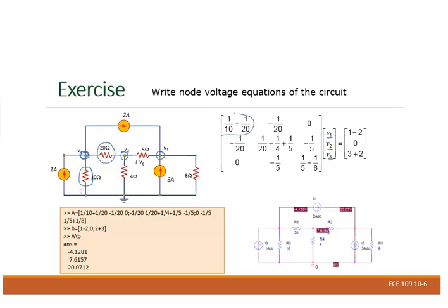That's what you have right there. Between node 1 and node 2, we have 20 ohms, so you're going to have negative 1 over 20 here. Between node 1 and node 3, we don't have any elements, that's why it's 0. It will be equal to plus 1, negative 2. So that's why negative 1 is right there.